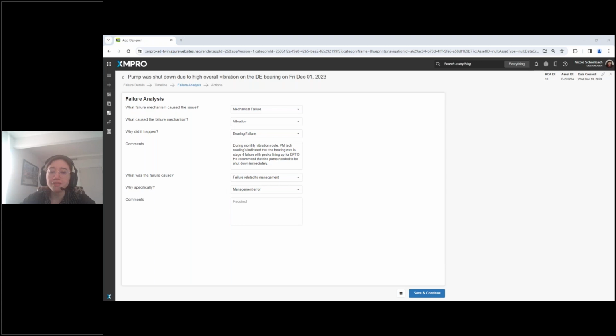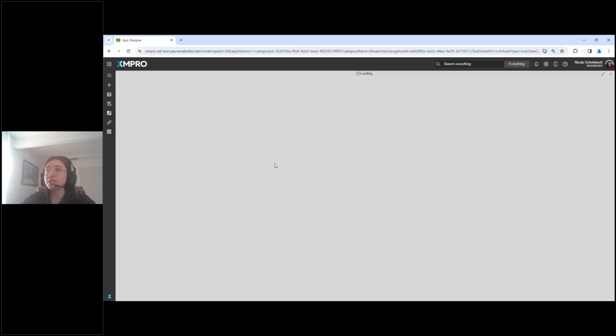So after you've evaluated with your team, you leave some comments. And apologies, definitely because of this unplanned failure on another piece of equipment, all hands were on deck. This PM was missed, and unfortunately, because this PM only happens at a low frequency, it was not known until the bearing was in a stage 4 failure that was going to cause an unexpected failure. So this is your cause map. Once you're happy with this, you can go to save and continue.